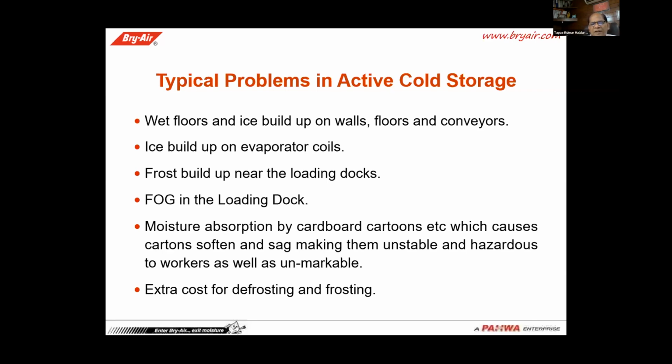Frost builds up near the loading docks, and there is fog in the loading dock itself. Then there is moisture absorption in cardboard boxes, cardboard cartons. We find that all the products are put in cardboard cartons, and from the top, water is dripping down on the cardboard carton, and it gets damaged. So this creates a problem for the cold storage. And defrosting and frosting is extra cost.